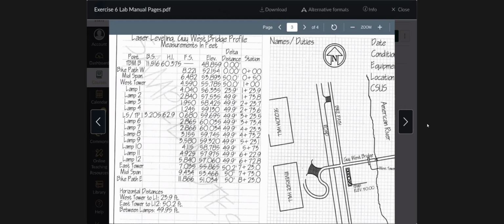You put it on a tripod, you eyeball it to get it somewhat level, turn it on, it levels itself, and boom, you've got an instant plane of horizontal light. Okay. So it goes really quickly once you figure out how to move the receiver up and down, move the bracket with the receiver attached to it up and down the rod. Okay.